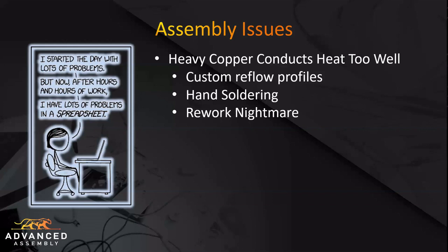Some issues that heavy copper PCBs have when it comes to assembly is that obviously heavy copper conducts heat a little bit too well. Essentially they act like a giant heat sink. They take much longer to heat up and much longer to cool down than regular boards.